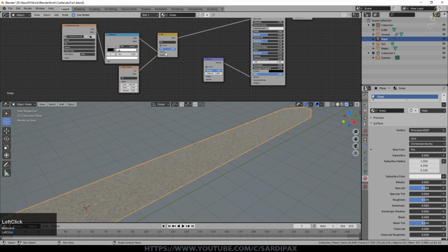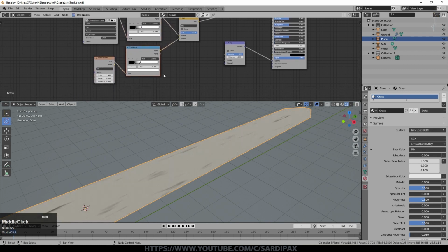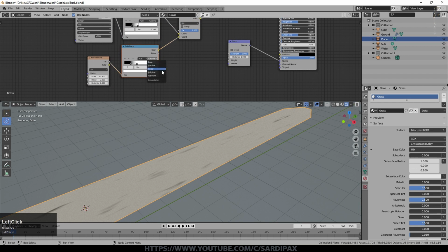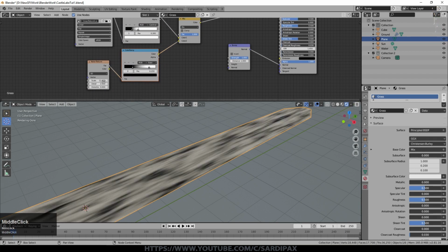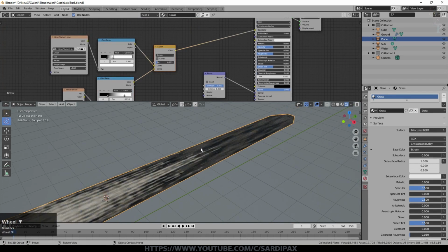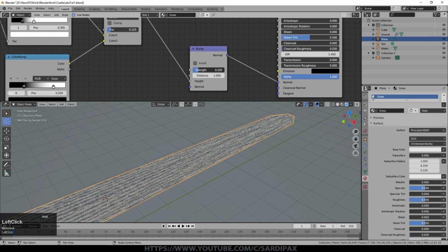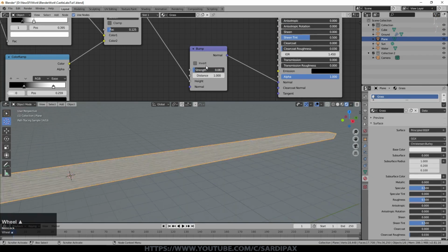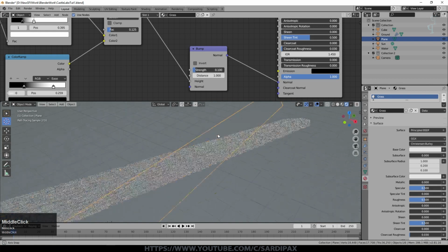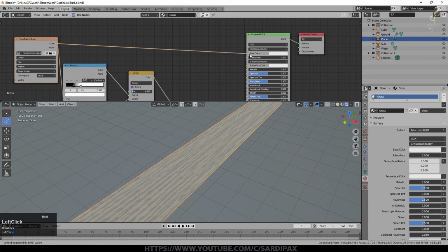We'll turn the noise texture up a reasonable amount. I'll just go over completely to the noise first of all, and I think I'll add a color ramp for that too. This isn't really essential detail. I'm going to go softer with this noise, so we'll go with ease, and I've only got a scale of about 12 at the moment, so we'll go up to 15 just to make sure there's plenty there. So now you can see we've got some random noise overlaid with the grass texture itself. We'll take that into the height, and that's really just bump we're seeing now. I've taken the texture off, and we'll turn the strength down quite a bit. So it's really just to have a little bit more, perhaps 0.1, some kind of surface texture rather than it just be completely flat.